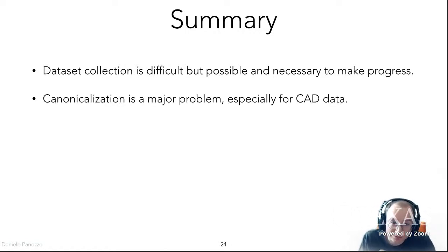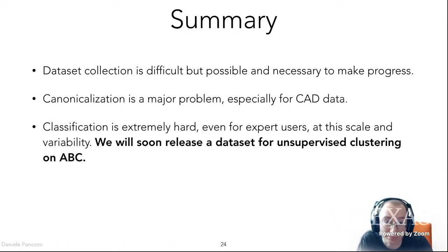Another issue that is specific to 3D data is that conversion between different formats is very hard, and I believe it's useful to have tools that allow you to go at least to one canonical format, which for what we are doing is a triangle mesh. So we can take different formats, clean them up until we get a triangle mesh, and then have additional procedures that convert it back to whatever other format you want. But I think focusing on a specific one will allow us to have something that is more reliable and more robust, and still sufficiently flexible to support a variety of applications.